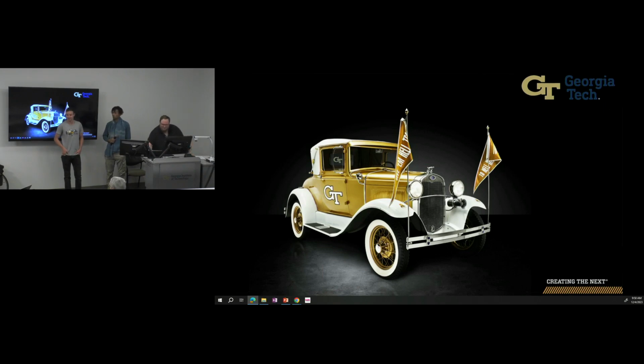You could probably trace your particles going back and forth, see if you get Poiseuille flow. It looked pretty uniform across the cross section. For Poiseuille flow, you need what's called the startup length, like 30 diameters. It'd be in the cross section, not the top that we were watching.